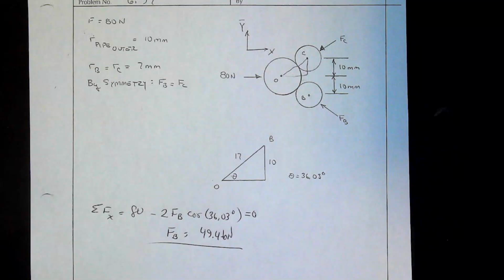So what does that mean? It says this piece down here is pulling down on this one. It's pulling it over this way. Well, that means this piece is pulling up on this one and pulling over this way. Equal and opposite. When you do a free body diagram, when I drew these in, that was a free choice. But the moment you draw those in, you draw these in too, going the opposite way. That's not a free choice. Pick one, that determines the other. All right.